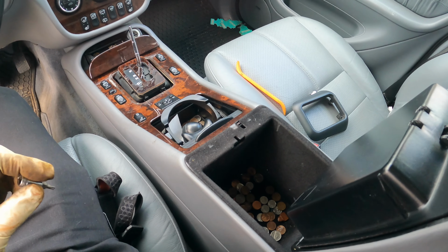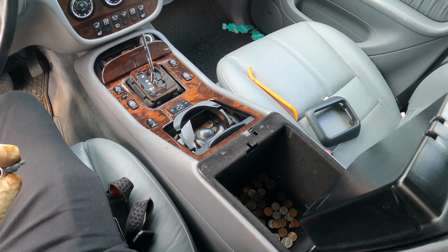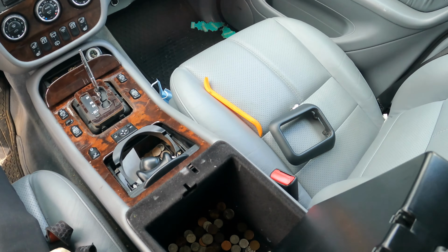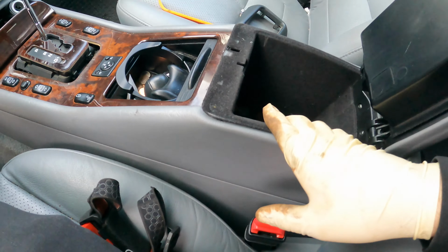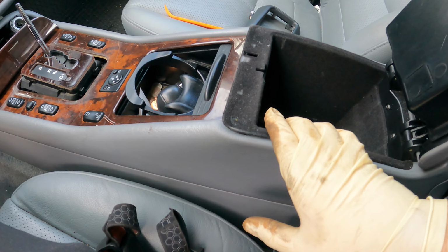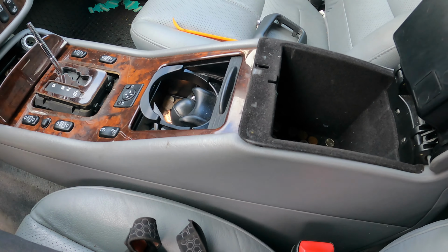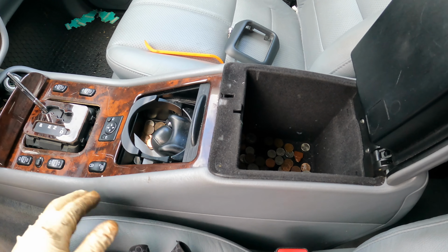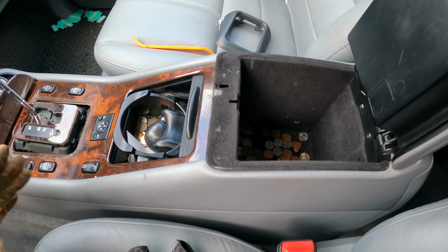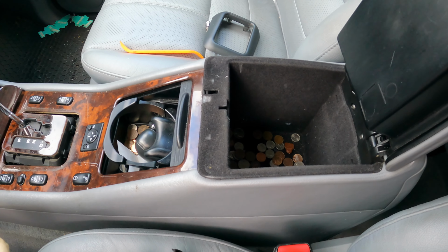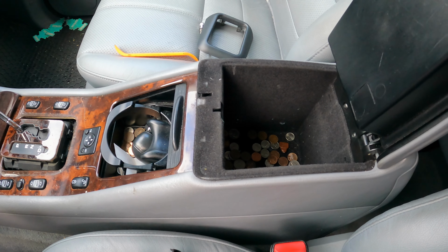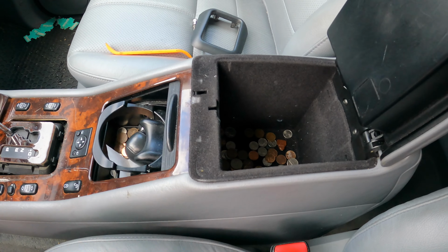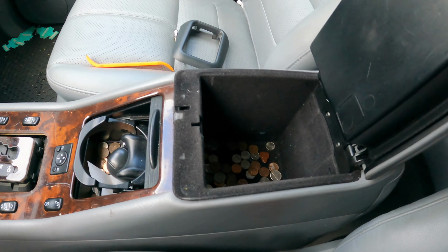So I disconnected everything from the bottom. What I want to do next is remove the center console, get access to that module, and check the wires there. And I might do a resistance check between all the wires. So far, I'm thinking that motor is bad, and I do have another car here, so I can swap it from. Which is good, but I want to do a resistance check between them first.